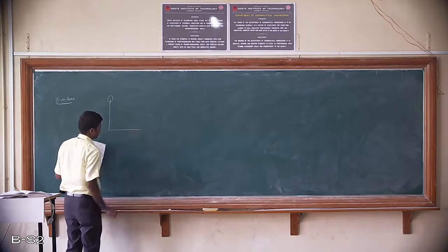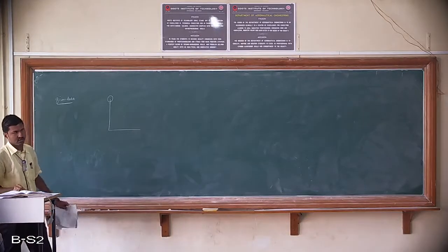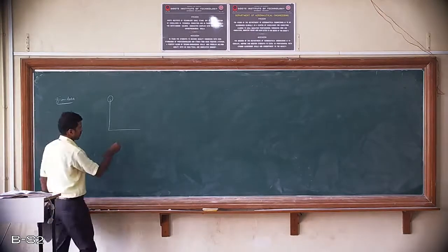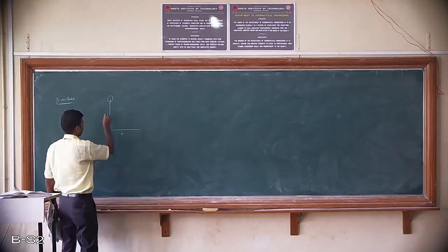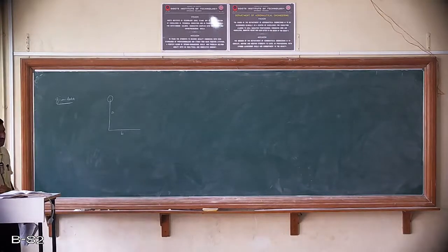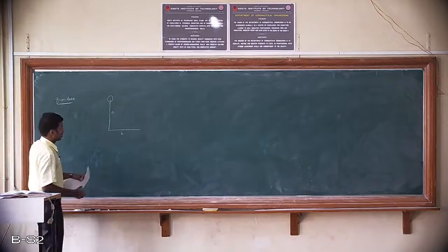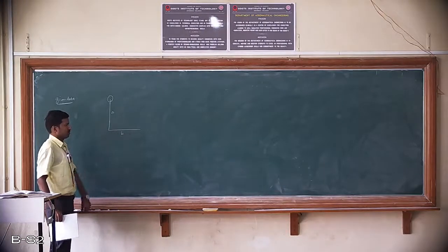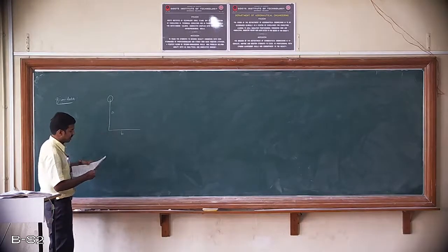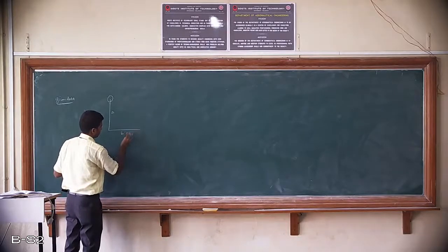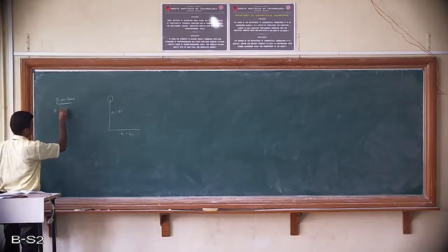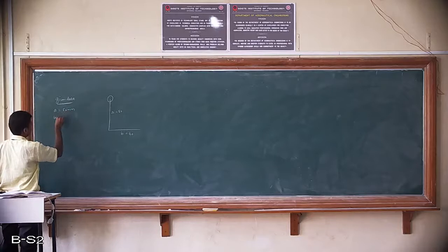What is the notation for the horizontal arm? In the derivation of the Hartnell governor, the horizontal arm is denoted as B and the vertical arm as A. It is clearly denoted there, so please go through the derivation. In this problem statement the lengths of the horizontal and vertical arms of the bell crank lever are 40 mm and 80 mm. So B is 40 mm and A is 80 mm.